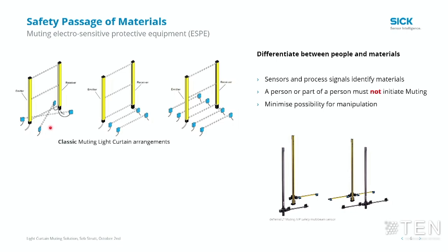Slightly problematic, but I'll talk about that in a minute. Or parallel beam entry-exit systems, and the one here has 2 sets of parallel beams either side of the light curtain. This allows a pallet to move both into and out of the light curtain. It's bidirectional. The middle example shows a unidirectional muting system where the pallet breaks 2 beams and enters the hazardous area. And just below, in the bottom left and right, are out-of-the-box solutions that you can purchase that fulfill that functionality.